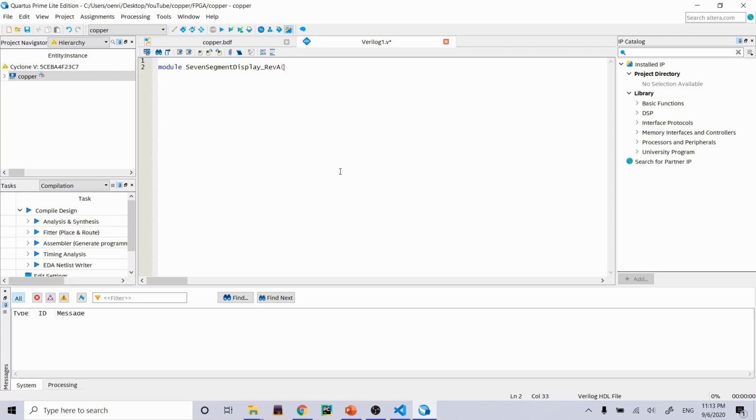All it's going to have is just outputs, because all we're writing is constants. So let's go ahead and make an output for each one. And I'm going to call it display here, because it's a 7-segment display. Display 0 is the whole one, so this is actually going to be a bus of 7 bits, and we'll get there. So let me just define all 6 of them.